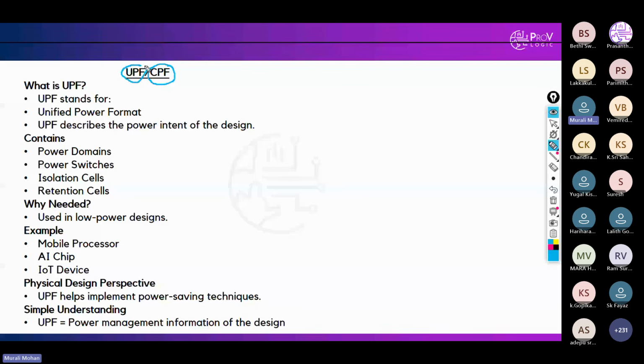That means it is predefined. Further, this UPF and CPF is classified into three types. One is golden. Okay, next is supplementary. Next is incomplete. Incomplete means we just write some basic UPF code and script and proceed with the stage, and it is supposed to be changed in the further stages. Supplementary means, if I take the UPF as an input for my synthesis, I can extract the UPF from the synthesis. Okay, whatever the extracted UPF is there, right?